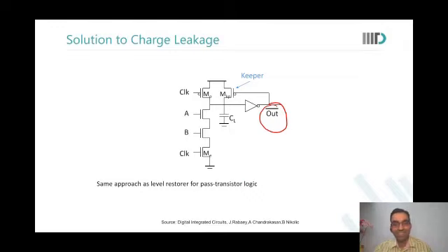Right. For the worst case sizing, you have to size the keeper at fast NMOS, slow PMOS, and at high temperature and high voltage, so that leakage is maximum, and at high voltage and high temperature the drive strength of the PMOS would also reduce. Yes, sir. That is the place where you will size the keeper.